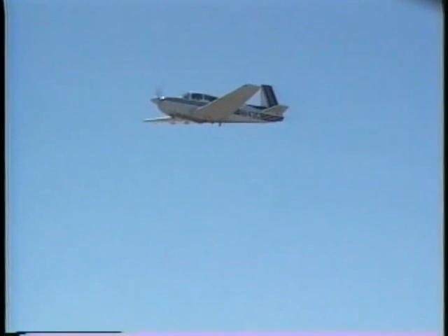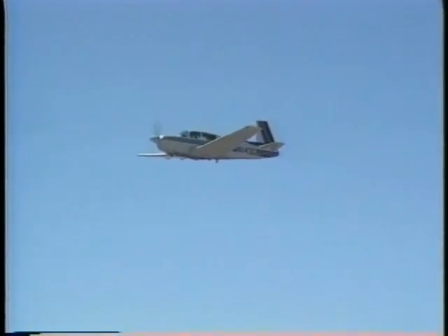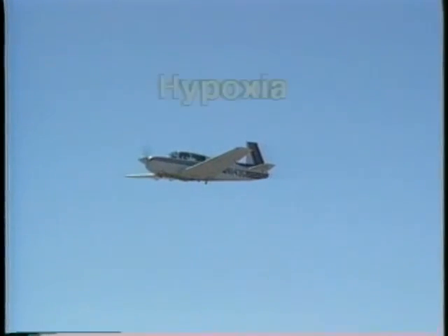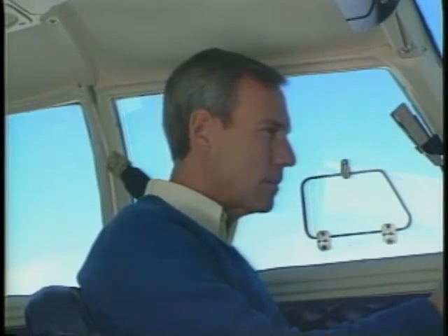If the oxygen system fails during a flight, or if oxygen is not used for high-altitude flights, you may suffer from hypoxia. Hypoxia is caused by a lack of oxygen. Symptoms for hypoxia vary from one person to the next, but one of the first things to be affected is your judgment. Here is a list of the common symptoms.